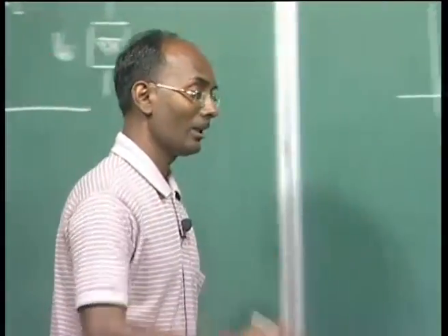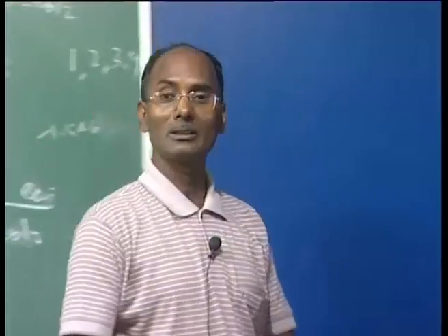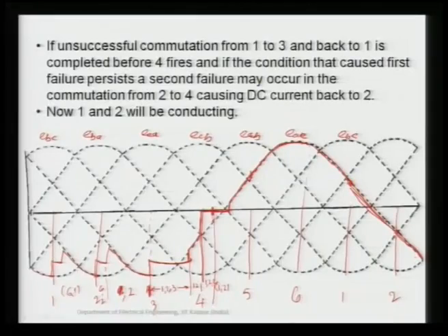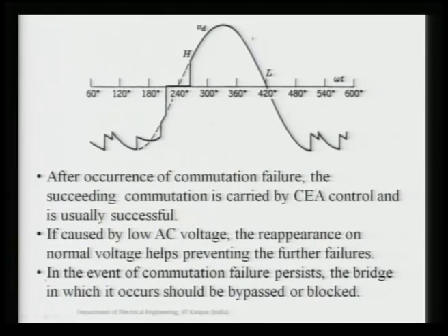Now you can see the scenario here is totally different from the previous one in the double commutation failure. In one cycle, 2 commutation failures occur. This is a very, very severe condition of the inverter, and it should be monitored very properly. So that's why I have written the event in this figure, basically similar to what I drew, because it was not very clear.